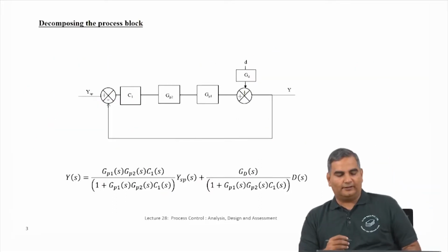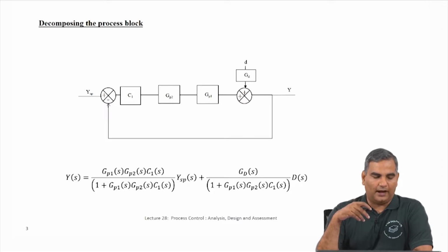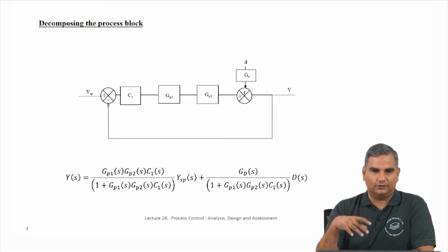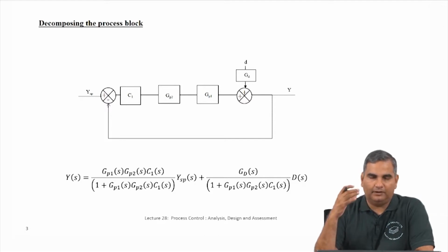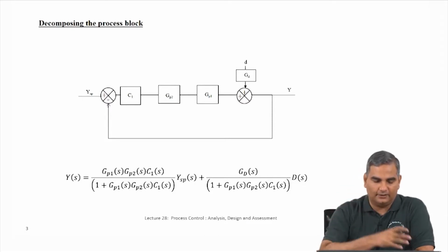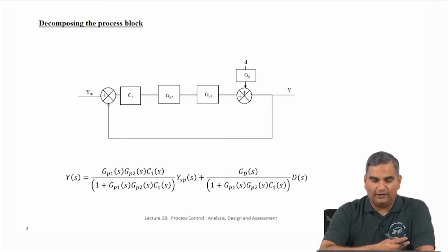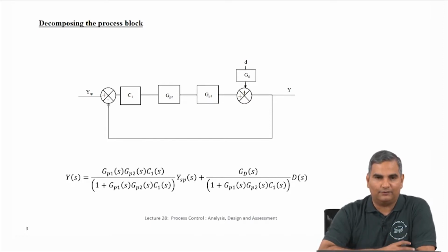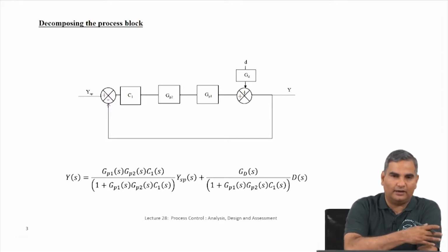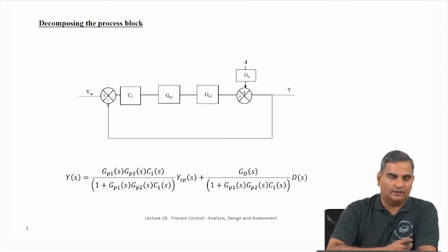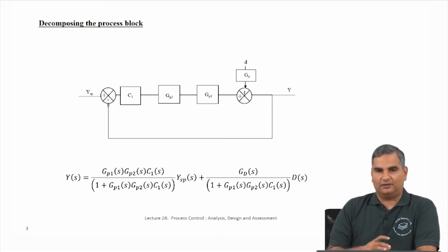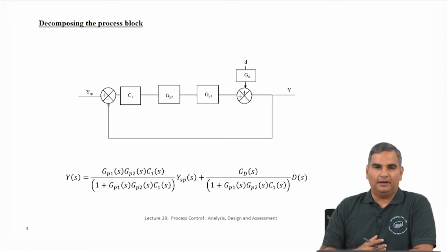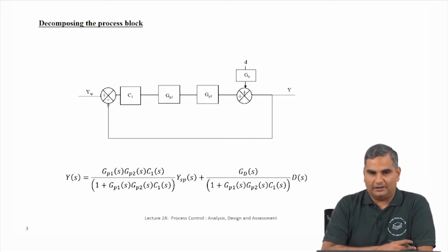Now, as I said before, I am going to add more details to this block diagram, and you have to remember that if you are adding more details to a block diagram, you should have more information that can be used by these details. If I do not have any more information than just a control variable and an output, there is no point in expanding this diagram, because the expansion has to be in response to some extra information that we have.